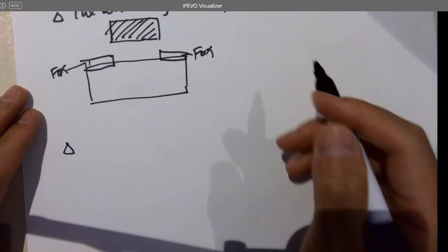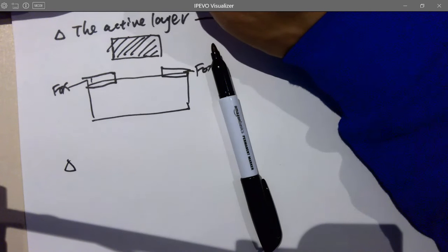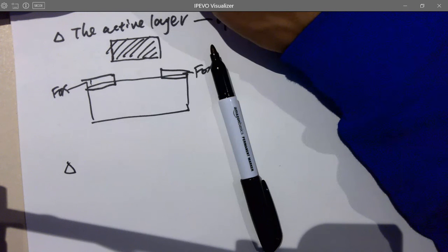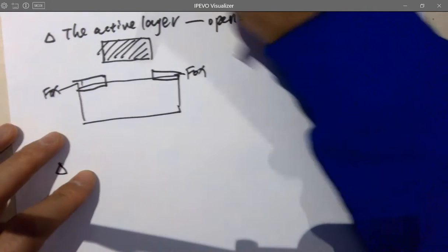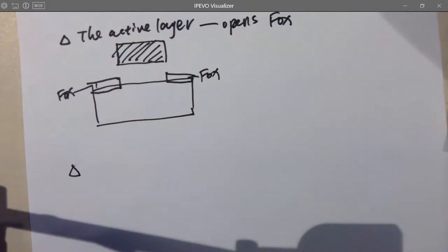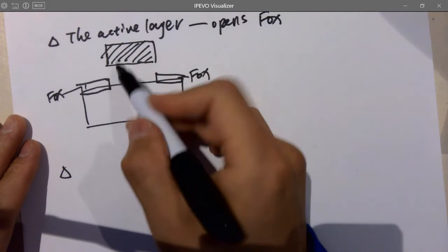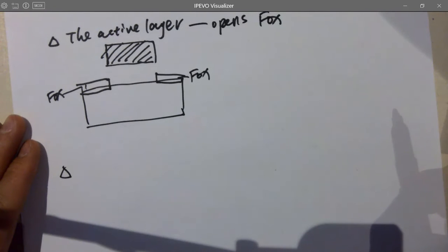You may have noticed this in the Electric VLSI layout view. There are two layers for the N+, so take a look at it when you are doing the lab on Tuesday. It has the active layer, which is exactly the area that will be doped with N+ or P+.